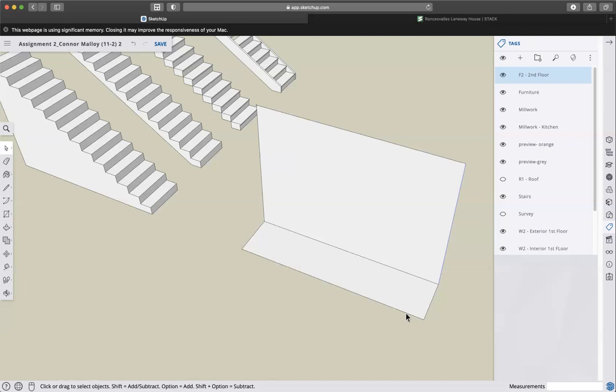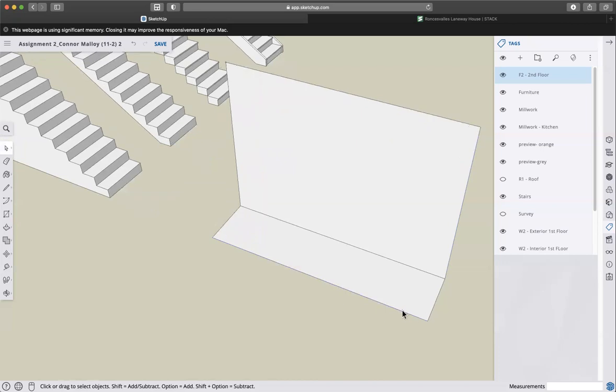So I can take the same tool. I'm going to select this bottom line here. Select the bottom line. I'm going to right click, click divide. And you can see I can move my cursor back and forth to show how the actual segments work. So that is how I get 14, or I can just simply hit 14 and enter. And again, you'll notice when I move my tool back and forth on the inside, nothing shows up except for the midpoint right there. But now that I've segmented, it shows me all of my endpoints here.